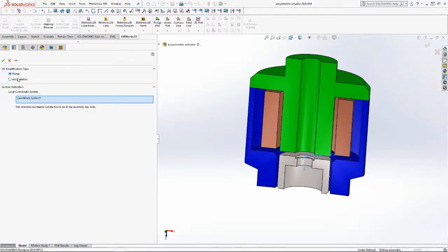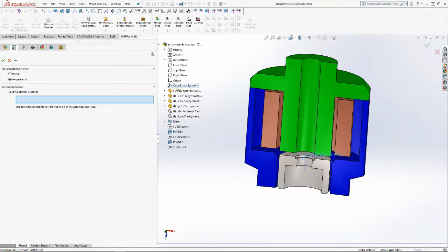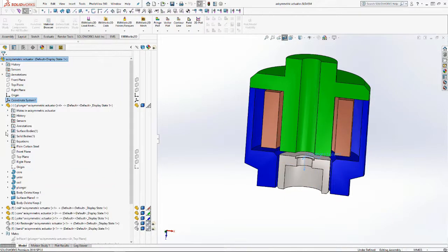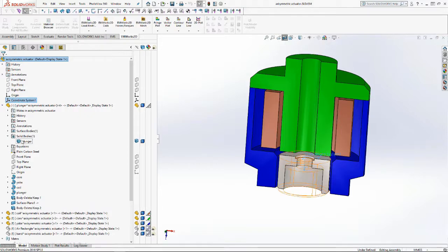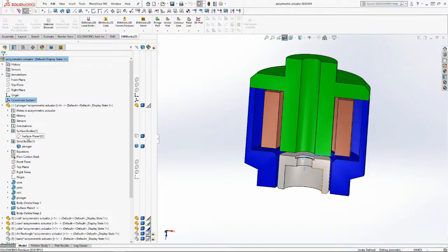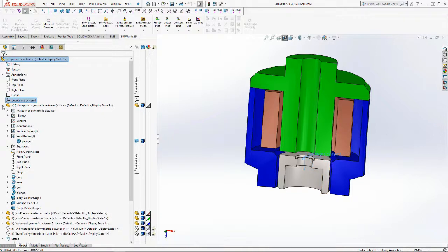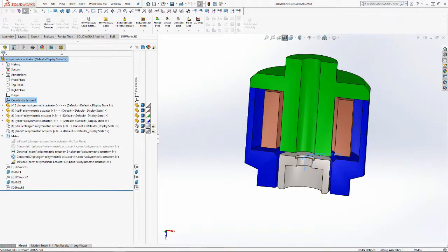Let's choose the symmetry type. It's axisymmetric. Then select this coordinate system, then validate. The software will create a 2D geometry from this 3D geometry. It will do a cut of your model or extract a 2D model from the 3D geometry. You don't need to perform any other steps, and you won't lose your 3D geometry. So you will keep using the 3D geometry, and we have the surface created as well. So we can have both 2D and 3D geometries in the same model.